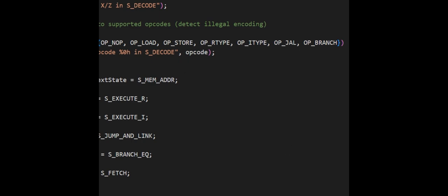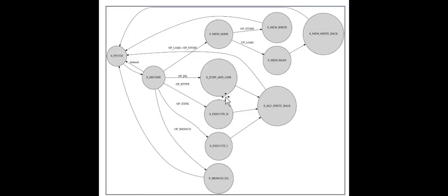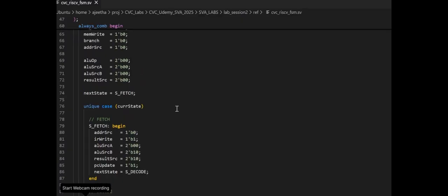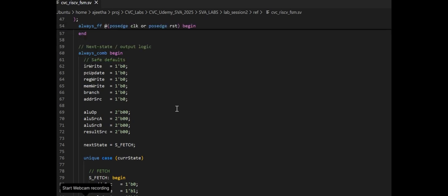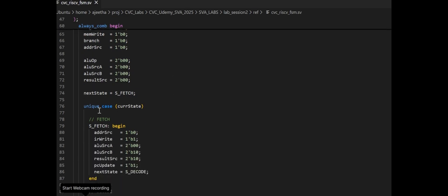And in this solutions part, I want to show you that I can actually implement some of these as immediate assertions and show how they simulate in a typical simulator. As an RTL designer, we implement assertions inside the RTL as immediate asserts, and there's an always_comb, and there's a unique case. Probably some of you are familiar with SystemVerilog RTL constructs. This actually has an implicit SVA that you will see in our simulation.